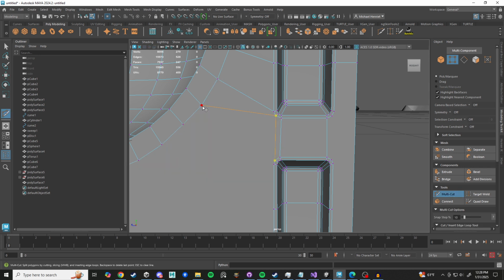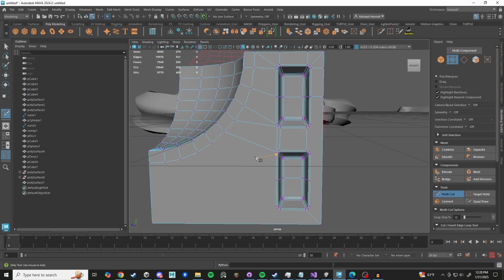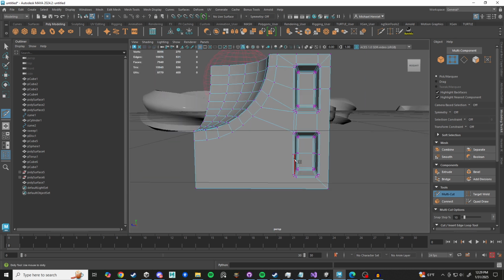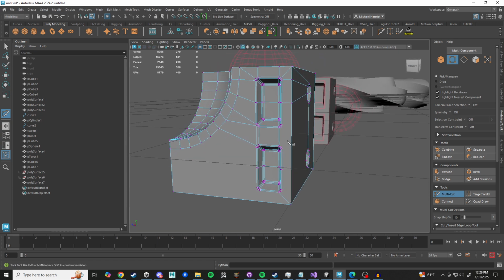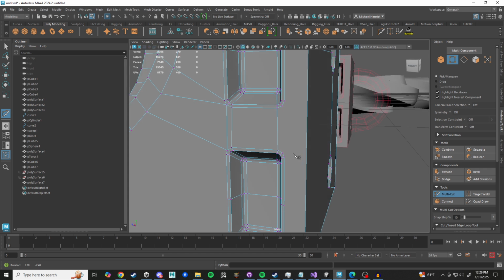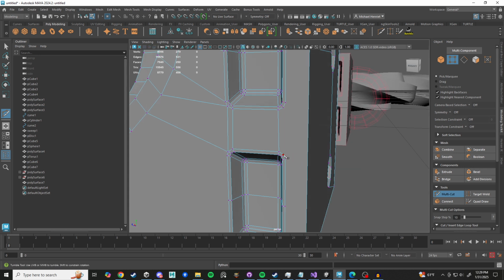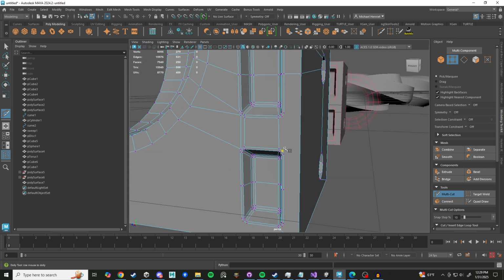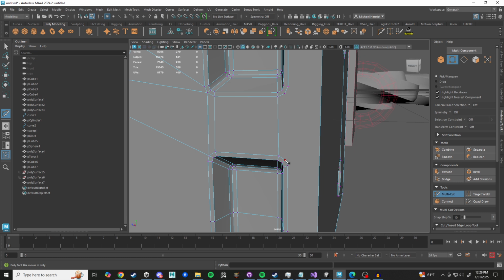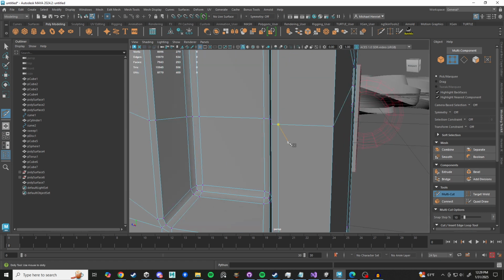So that's working with Booleans. They're a great tool that you can't make certain shapes without, but they're gonna be a bit of a pain, because they're not going to behave as bulletproof as you would expect, you know. You still have to solve the topology and stuff.